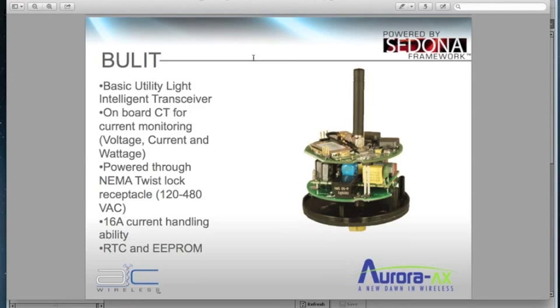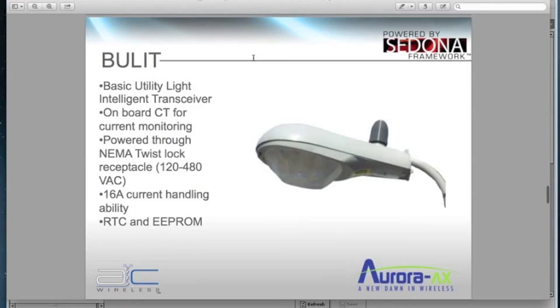The only offset that would have to be accounted for is midday storm override or an event that would call lighting to come on in daytime hours. And for that, we use photocell arrays around the network that communicate back to the JACE. And that would require communication from the JACE to the network. Now, we have had multiple applications for this product.